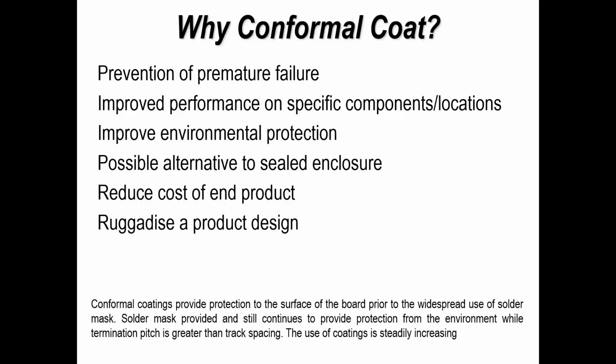It can be used as an alternative to putting a product in a sealed box, and it may well be a cheaper option, but it may not be the right option. So again, you've got to look at both of those options, but certainly it's an alternative sometimes. It can reduce the cost of the end product if you are substituting a coating for perhaps an enclosure, but again, it's very design specific.